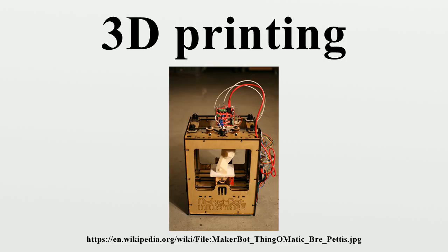Another 3D printing approach is the selective fusing of materials in a granular bed. The technique fuses parts of the layer and then moves upward in the working area, adding another layer of granules and repeating the process until the piece has built up. This process uses the unfused media to support overhangs and thin walls in the part being produced, which reduces the need for temporary auxiliary supports for the piece. A laser is typically used to sinter the media into a solid. Examples include selective laser sintering, with both metals and polymers, and direct metal laser sintering.